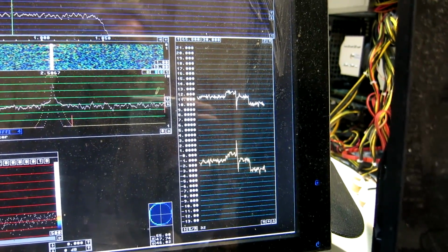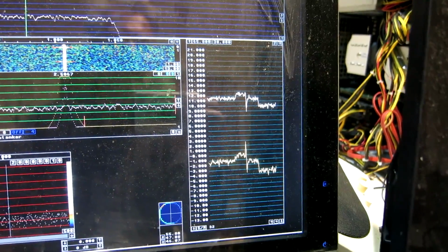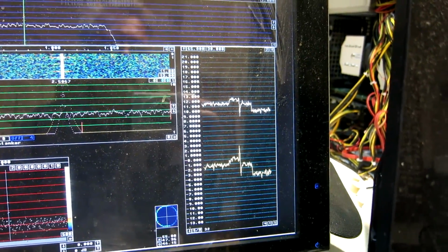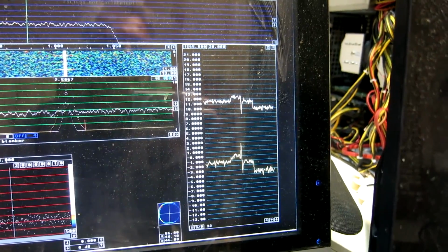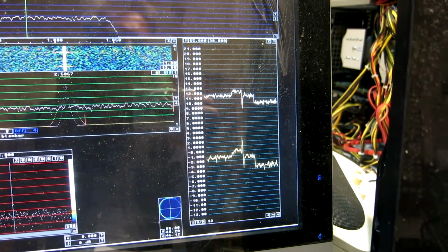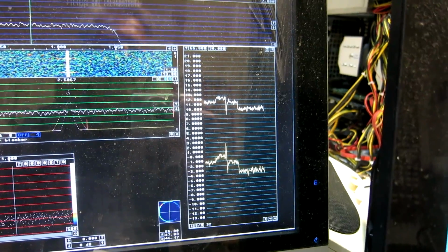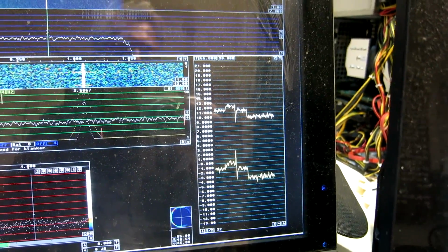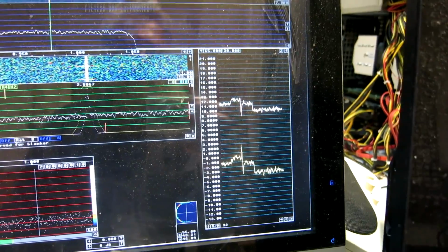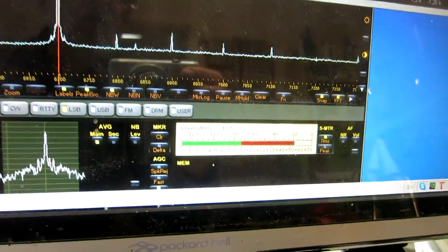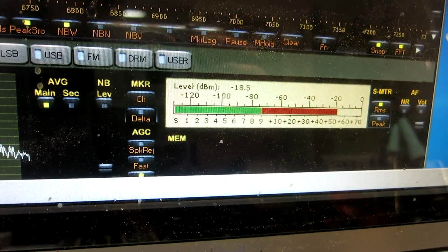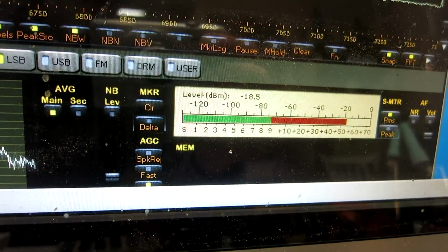And of course, I don't get performance back because I have triggered the AGC and there is some hysteresis there. So I have to make the signal a bit weaker to make the AGC shift its state. That means that the level I note for the 1633 is minus 19 dBm.